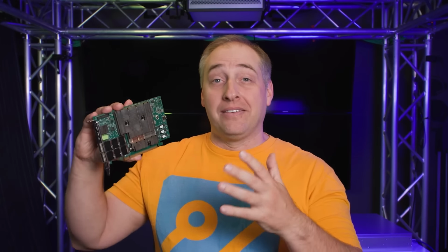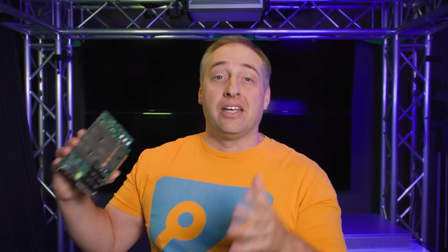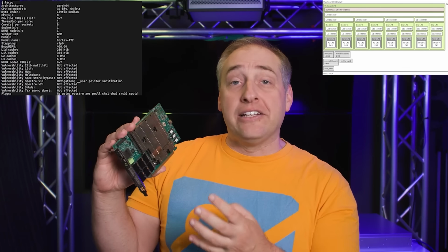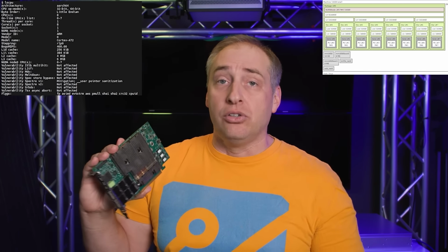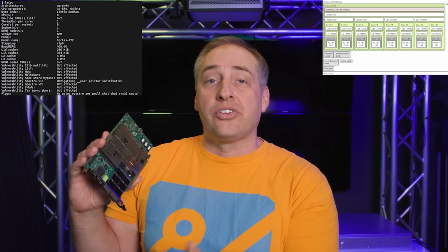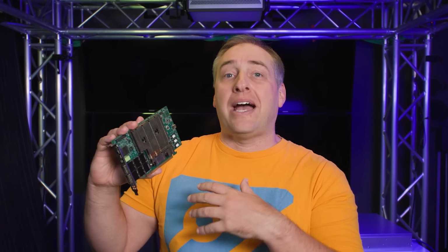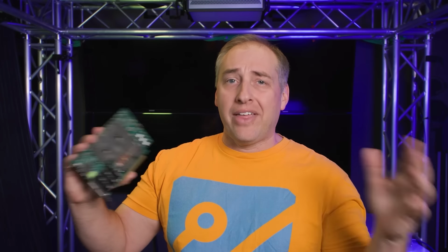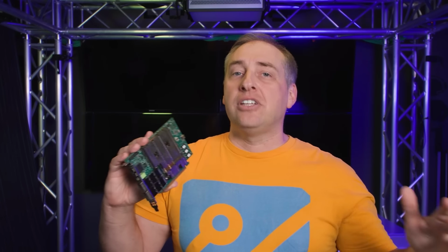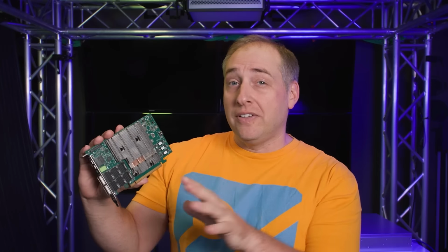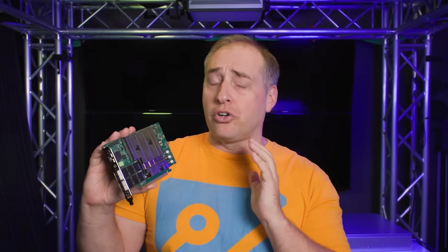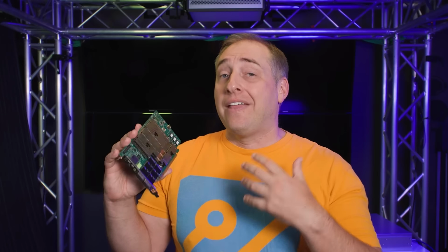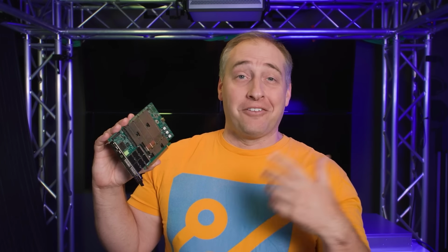But I just wanted to show you that the DPU is part of the development kit that you would get. And each one of these is actually kind of interesting itself because NVIDIA is using ARM cores even on its DPUs, and this particular one has 8 ARM cores. So this DPU actually runs all of your things like your network offloads. It can run your network overlays, encryption, all that kind of stuff on this DPU without actually hitting the host CPU. So the NVIDIA Bluefield series, and we'll have Bluefield 3 at some point, is super important to the overall strategy of NVIDIA, and they are in the system. We just didn't get to take photos of them.